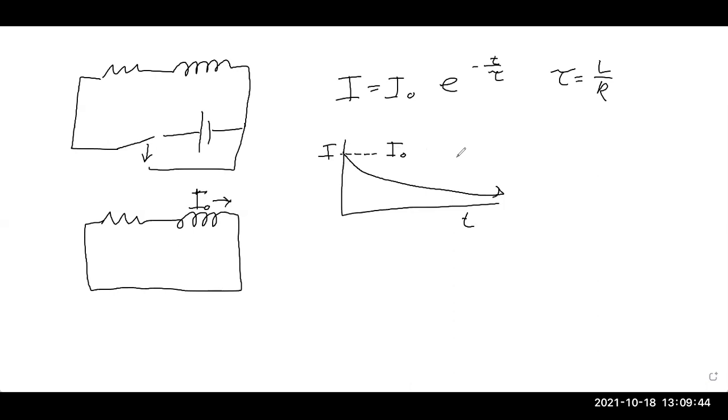So some differences from a capacitor. The greater the resistance, the slower it would be to charge something up. It takes more time to flow through a large resistor than a small resistor. A bigger resistor will have a bigger time constant. For LR circuits, the greater the resistance, the faster energy is dissipated out of this circuit, and the shorter the time constant.